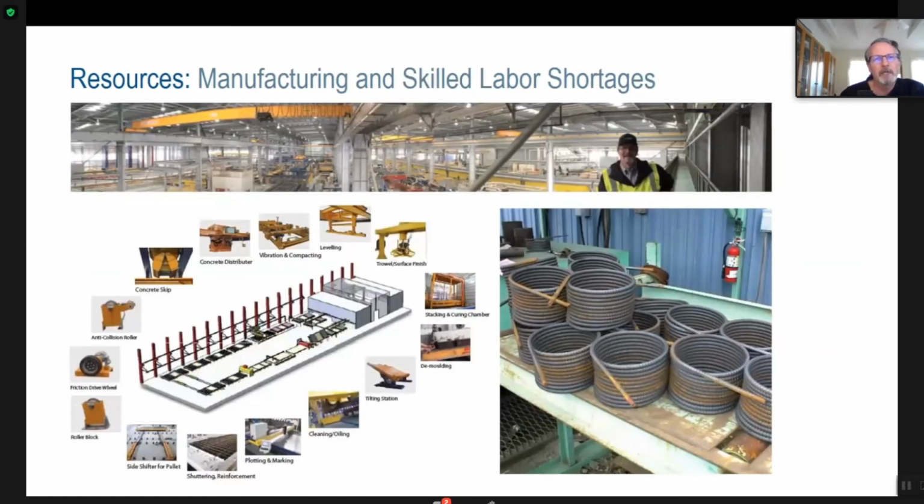So, you need to understand each station in a factory. Do they have kilns or not? And what's the size of component that can fit into the kiln? What's their tilting station like? Do they have essentially a 3D printer to lay down the concrete? Is it going onto a vibrating table to level it, or do they have to do a traditional process? In the back of the factory, are you seeing these coils of rebar that go into the machine or not?